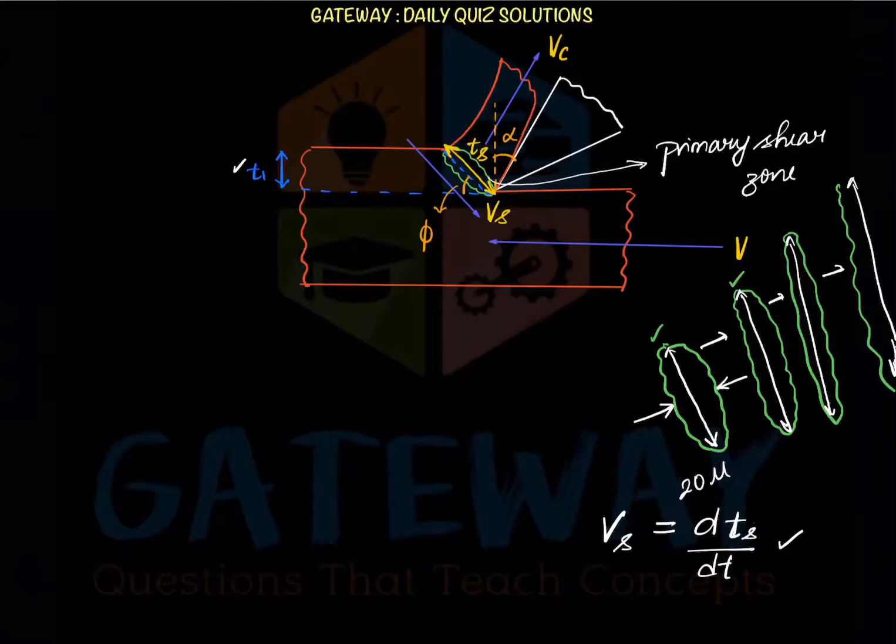Understand? With respect to time, how the strain rate varies, because here, as the metal tool pierces into the workpiece, the metal's ability to resist the tool will deteriorate with time. So in the course of this process, the stress acting on the shear zone is not a constant value, it keeps on increasing.